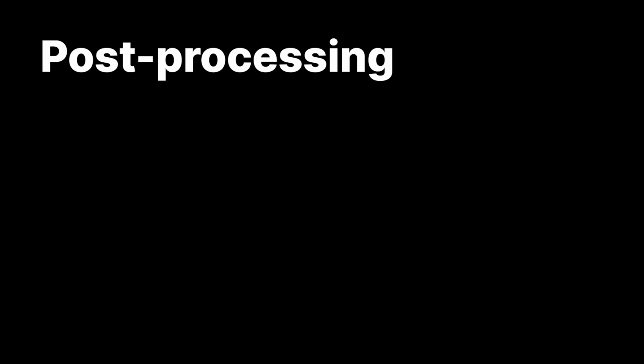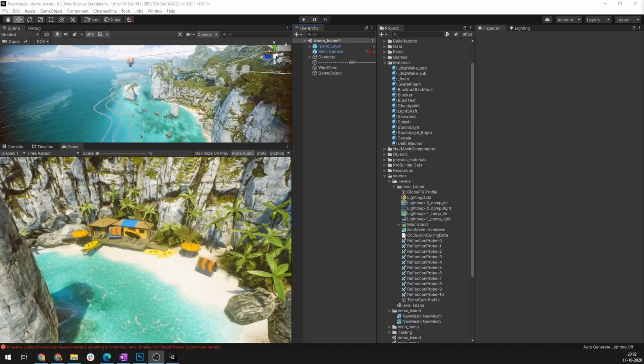Finally, we come to post processing. Post processing is a set of rendering effects that you apply based on your existing rendered scene before generating the final render. This means you get instant visual feedback for the effects that you choose. In URP, many rendering and post processing properties are driven by a volume framework. Your settings will essentially be organized in categories attached to the volume component.